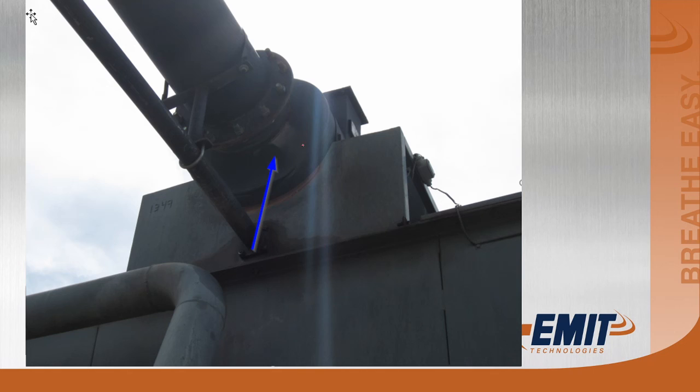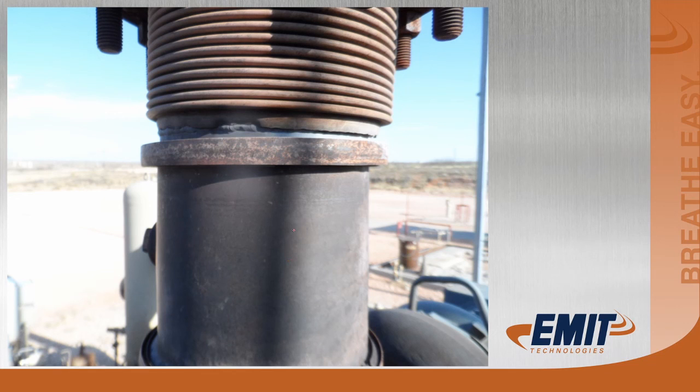Here's another example of just plain ash showing on the outside of the housing. You can spot that from the ground, and there's a crack right here. Just gotta weld that up. That's ahead of the catalyst element, and that'll cause poor performance on the catalyst. Here's a classic. Bellows broke off and somebody welded them partially, but again, right here you're seeing opportunity for oxygen to be drawn into the exhaust stream.